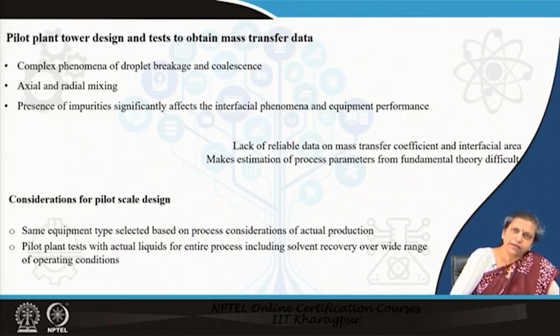Because the extractor involves the complex phenomena of droplet breakage and droplet coalescence, which is itself not an easily predicted phenomenon. Another thing is there is axial mixing and radial mixing. Then we cannot avoid any sort of impurities, and whenever there are any impurities, they significantly affect the interfacial phenomena as well as the equipment performance.